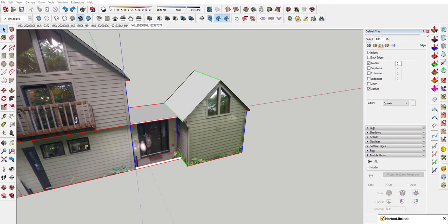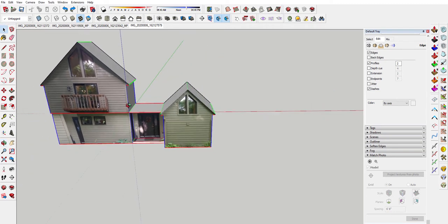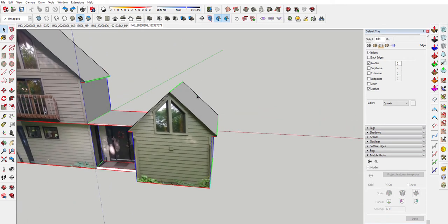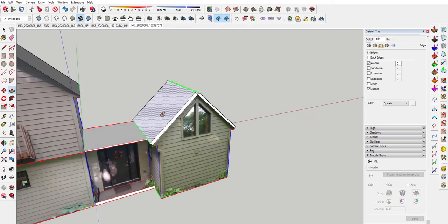So now I'm going to go ahead and put the roof shapes on. I'm going to just do a push-pull and get the basic shape, and then use that to create this center portion. I know the slopes here and here are the same, so I can do that really easily. And I like to do gable ends first before I try working on hips or valleys. So push-pull, tap the Control key, and I'm going to go up 4 inches. About a 4-inch fascia that was visible.